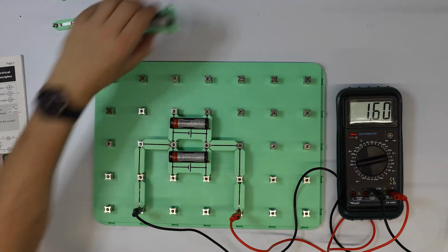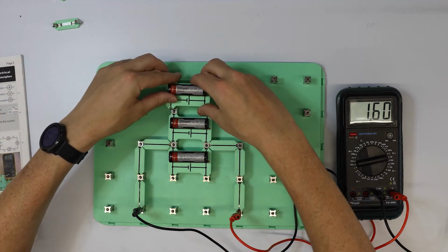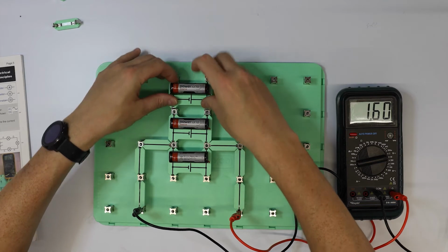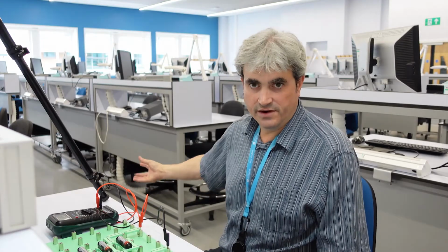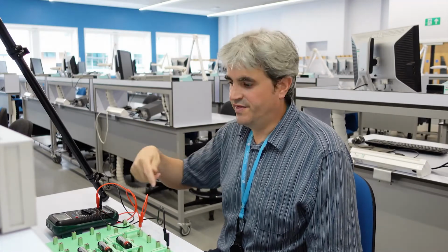What I can also do is add my third battery into the circuit again, so I'll put that in the circuit up here, click that in place, and once again I can see that that hasn't changed the total voltage across the circuit. So as I'd expect, if we didn't see a difference with 2 batteries, by adding a third battery in the circuit we're seeing that once again the voltage is unchanged. However, once again, if I had a very high current requirement, this arrangement would now be able to provide 3 times the current of a single battery on its own. So it actually gives us improved performance when we consider it in terms of the current that's available in the circuit.